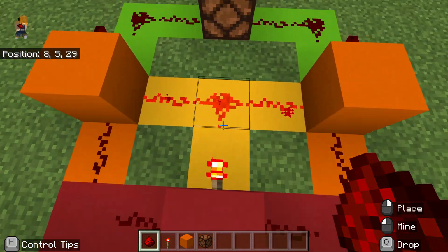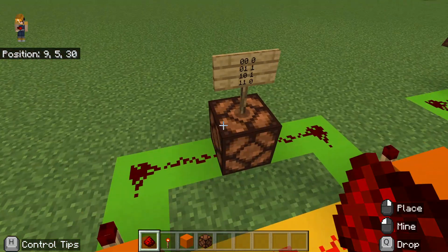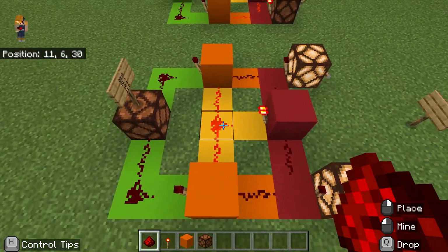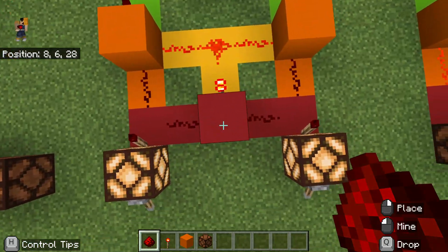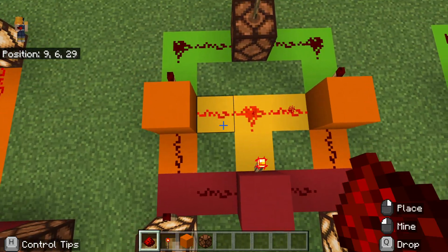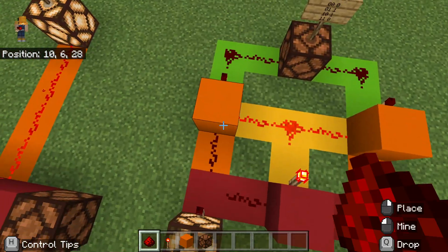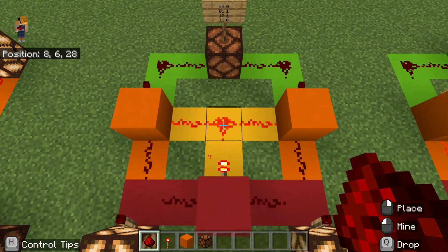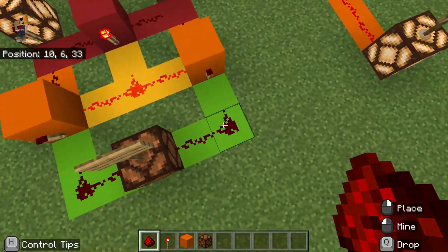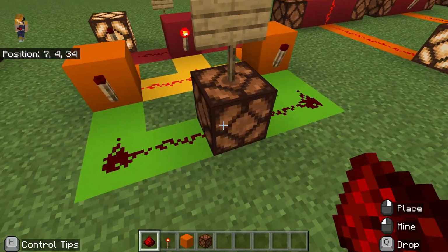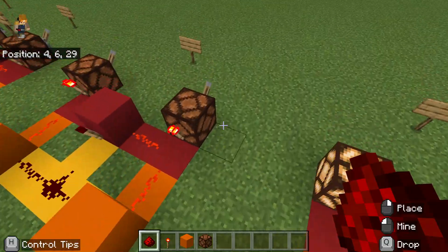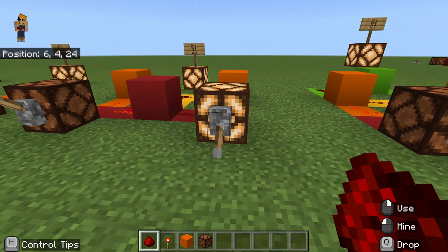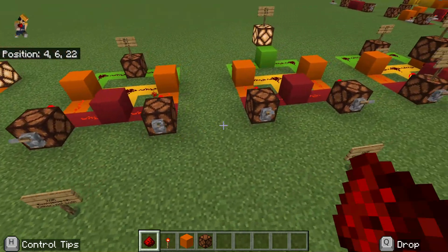So the output now will turn off these NOR gates, which is why the output is off when both inputs are on. That's how it's described. So red is the AND gate, orange is the NOR gate for the sides, and yellow is the NOR gate for the AND, and then you have your output wire to this. So that's how an XOR can work.